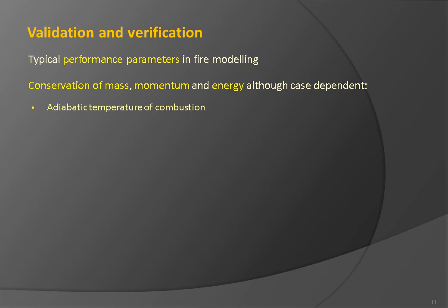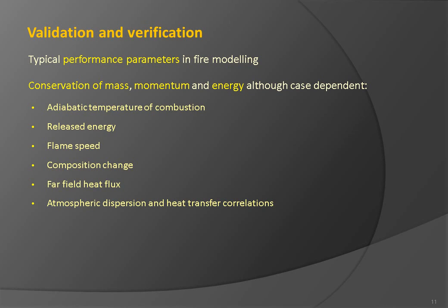Therefore, we can state that the adiabatic temperature of combustion shall not be exceeded, released energy shall not exceed the net reaction heat, flame speed should not exceed experimentally published values, composition change shall match the reaction rate over the simulated time interval, far-field heat flux shall not exceed heat flux associated with fire irradiation, different correlations associated with atmospheric dispersion and heat transfer shall hold, and we have to recognize that supersonic flow speeds are rarely associated with fires, especially in an open environment.